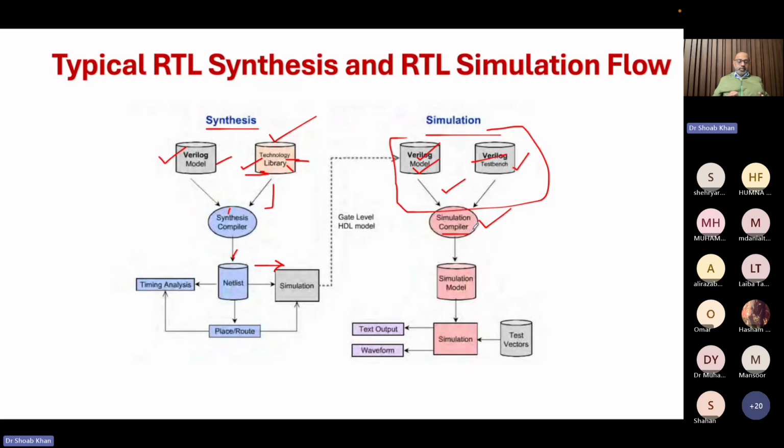Why? Because now it gets translated into very low level, gate level code, and for perhaps one line of code that you have written in Verilog, it might have generated thousands of lines of code to be validated and verified. So usually you have your test benches, a lot of test vectors that you generate, you do the simulation, and then you may look into the waveforms and the text file.